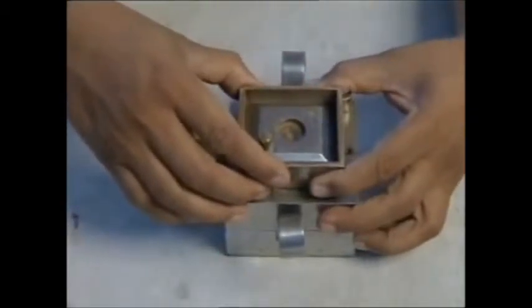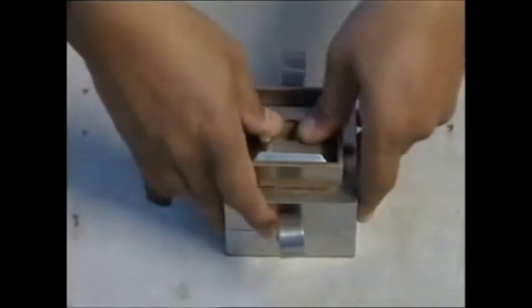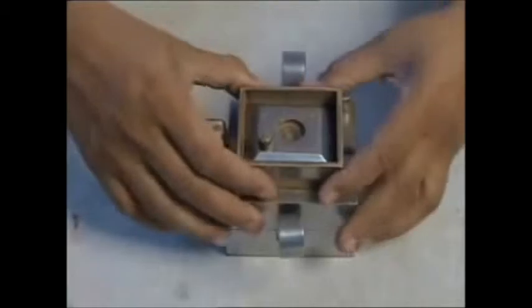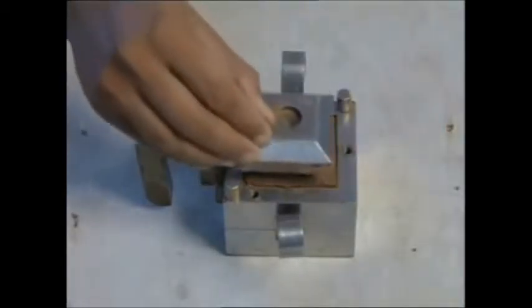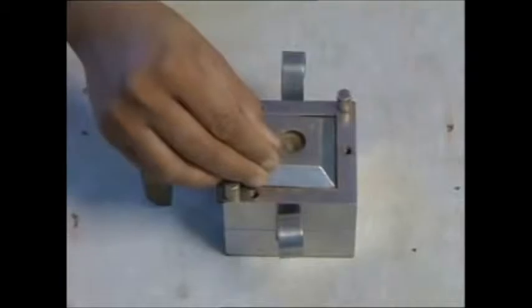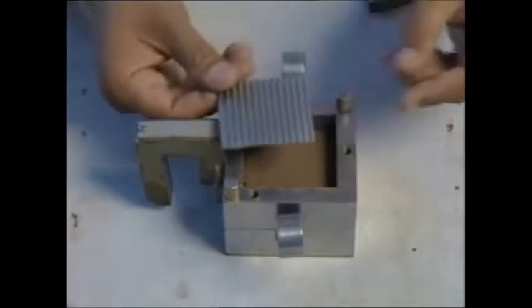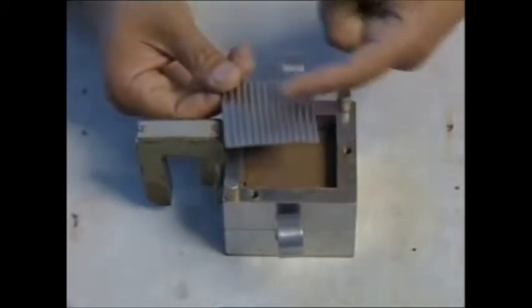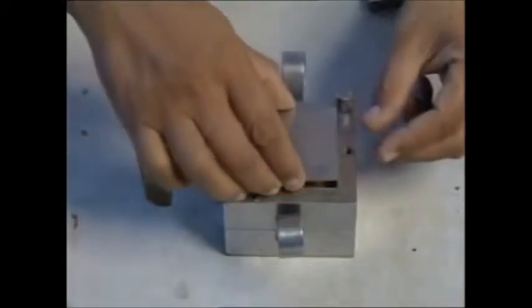After you push it, if it is well fitting down, you remove the sampler with the top cover. Then take back the cover, use it to push down the sample, and make sure it is fitting the bottom plate as I said. Also take the grid plate and make sure those grid lines are perpendicular to the direction of the shear.